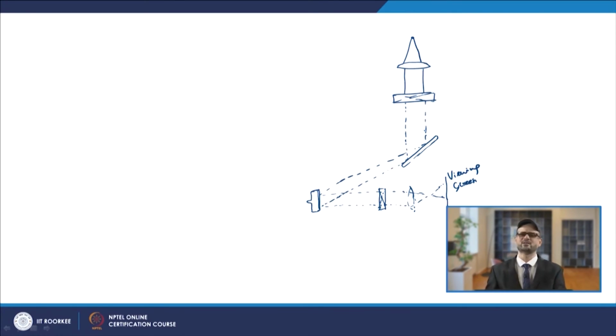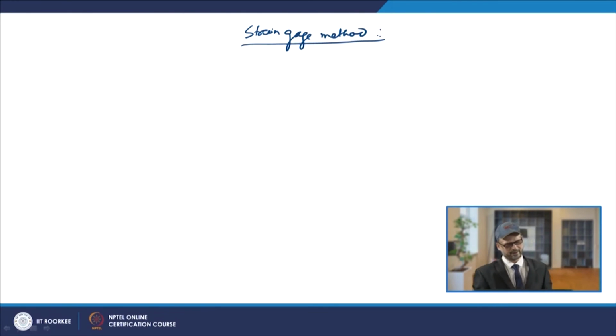Now the next method which is used is the strain gauge method. In the other two methods, you are basically drilling the hole and measuring those strains.